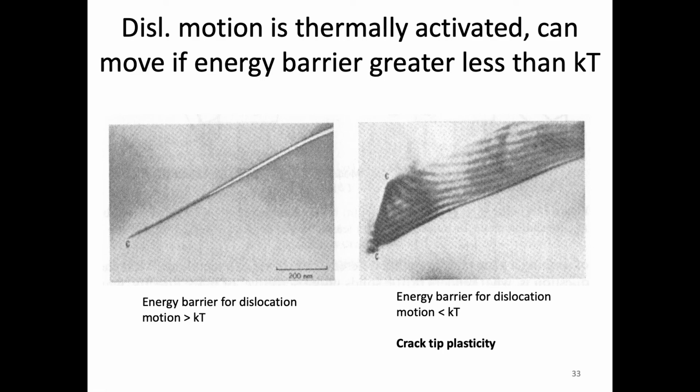And this is because, if you think about it, ceramics are very brittle, but they're also high temperature materials. So when we're using them in those high temperature applications, we also have to consider that we have more thermal energy. Therefore, in those situations, dislocation motion may be more of an issue than at room temperature. So it all really depends on the conditions under which you have these materials. If you have them at high temperature, we often have to consider dislocations in more detail.